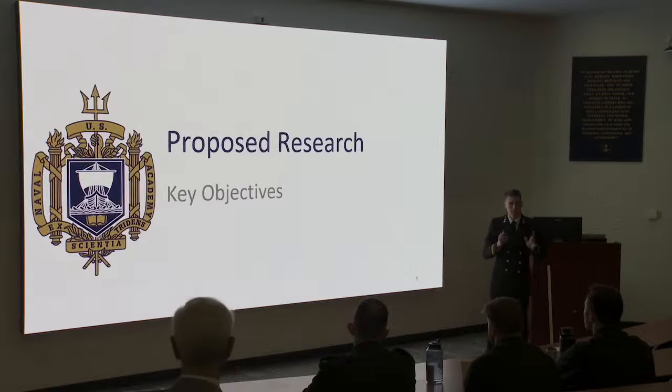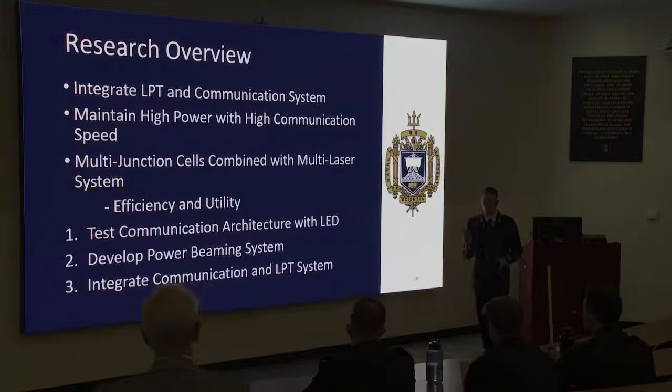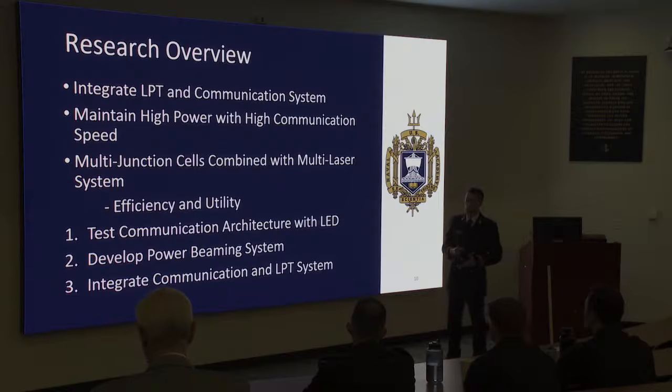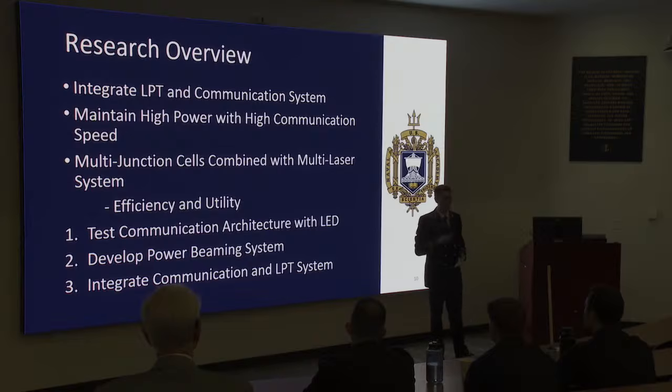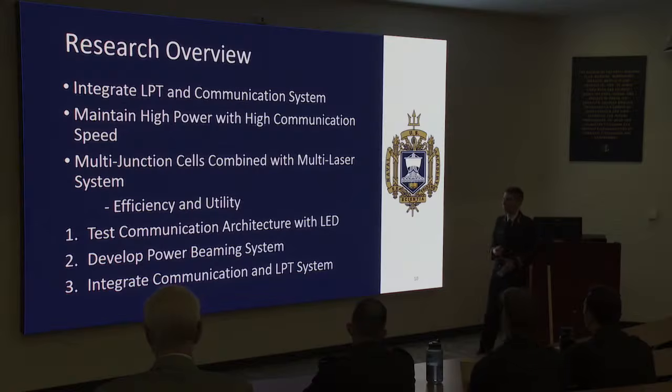Okay, now that we have a semi-firm foundation and we can kind of speak the same language, let's dive back into what this research is actually about: integrating the LPT system with the communication system. Once again, we're using that LPT system that I'm creating from the NPS research and modulating the lasers to create a communication link. This has to be constrained by maintaining the high power efficiency of the LPT system while also establishing high-speed communications. We'll be doing this using a multi-junction PV cell, specifically the same triple junction cell modeled by NPS, as well as multiple laser diodes, each matched to the different layers of the PV cell.